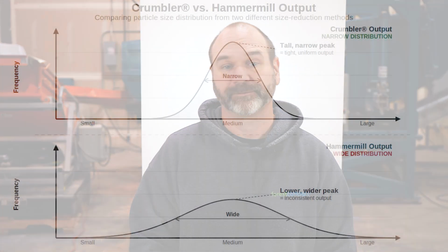When we're going into a dryer, it's the same kind of idea, to where distance to center makes a difference for how long the particle has to be in the dryer. The shorter the residence time, the less energy it takes. Therefore, it's a more efficient process to be able to dry smaller particles than it is larger particles.